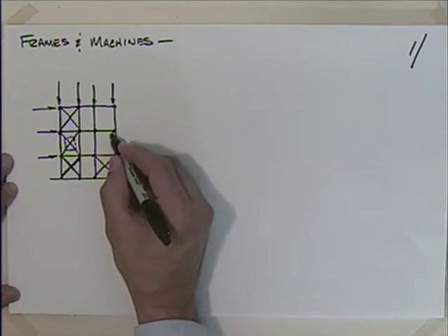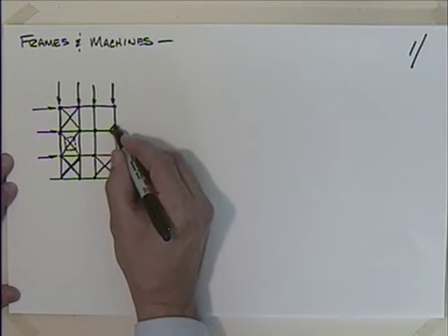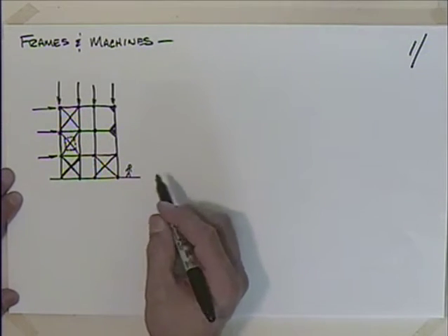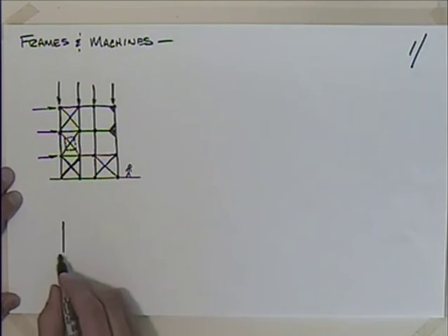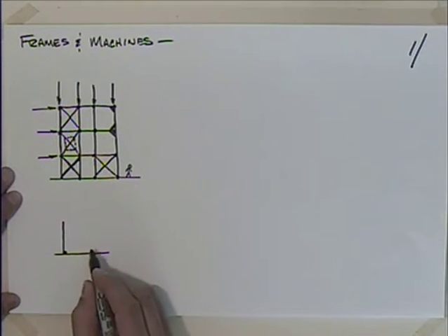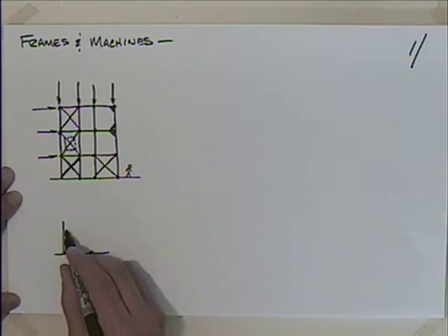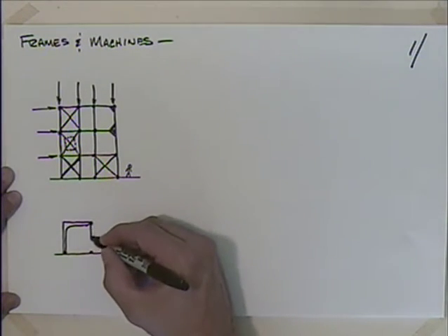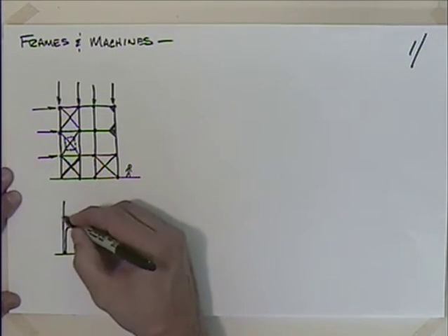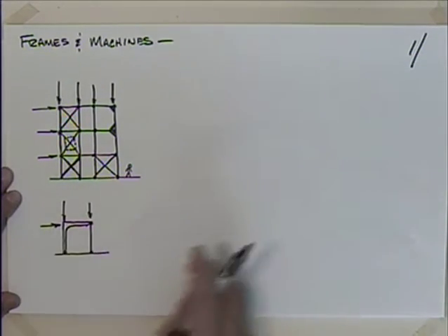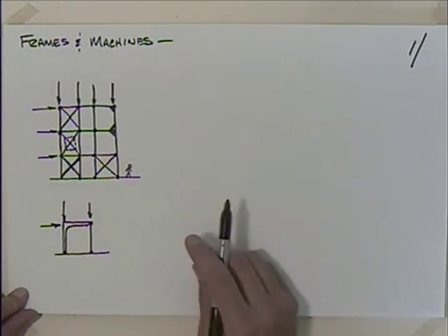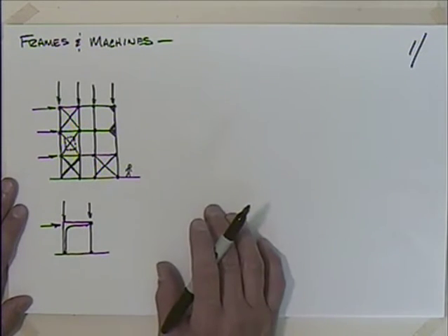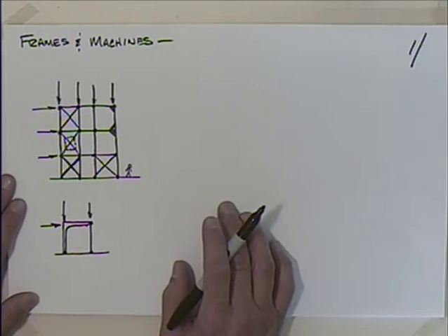So what they might think about doing is putting some gussets here and starting to brace these joints, and you turn it into a moment frame. So let me do this on a little smaller scale. Maybe you have something like this, and you build a frame like this. This piece is a frame, and then you could still have a two-force member there. And then as you put loads on this, this is resistant to bending. This is not a pinned connection there, and it will support those loads. So that's probably more from a structural vantage point, a civil engineering vantage point.